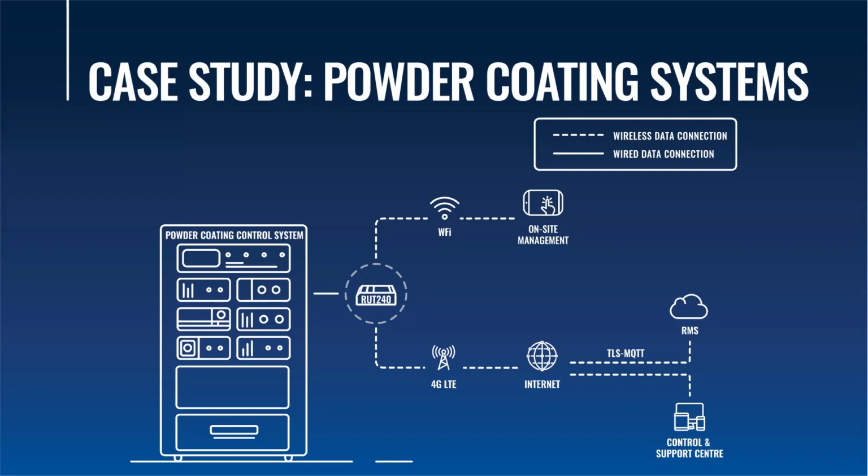They cost millions of euros, the professional ones at least. And they're very difficult to set up, and they're very difficult to adapt to the different things that you want to powder coat, so to say. And the difference in settings can have dramatic effect on the usage of the powder itself. Just a few voltage steps that you change can increase your consumption of powder by 20%, let's say.